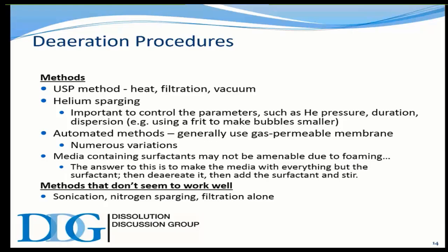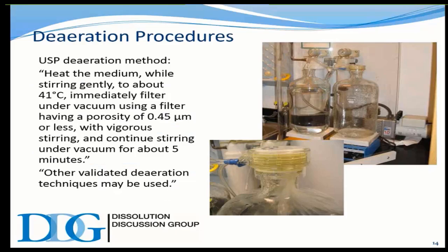You'll see some graphs and charts of doing some of these alone, like where you sonicate under vacuum, sonicate alone, or filtration alone, or potentially using nitrogen gas to sparge, which really forms N2 molecules, which are big enough to see and don't really do anything. So some things work and some things don't work. And this is why USP, when they mention their method, they also finish that up with other validated de-aeration techniques may be used. But anyway, the USP procedure.